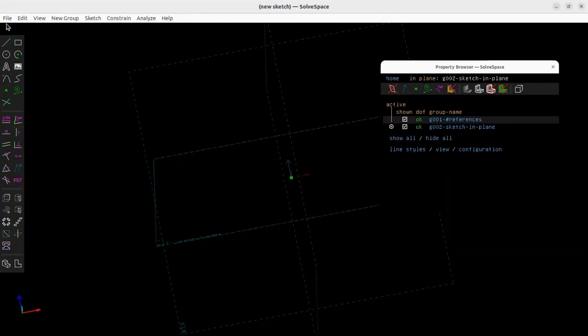So here on the left side, you can see all the tools that are available. The drawing tools, so you can draw lines, squares, circles, text, curves, and so on. Then here there are the constraints. So geometry constraints, so you can reuse your maths or geometry knowledge. You were learning about how to make things parallel, that there's an angle between lines, that something is perpendicular, all these kinds of things. You can use all that in CAD software. These constraints are all about that. You can make something horizontal, vertical, and so on.